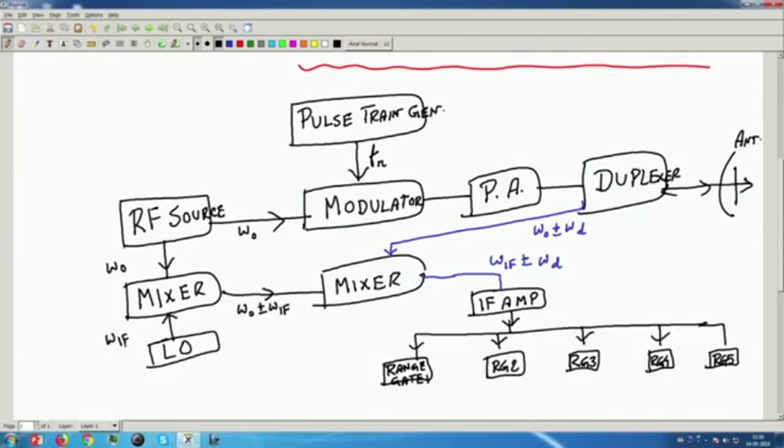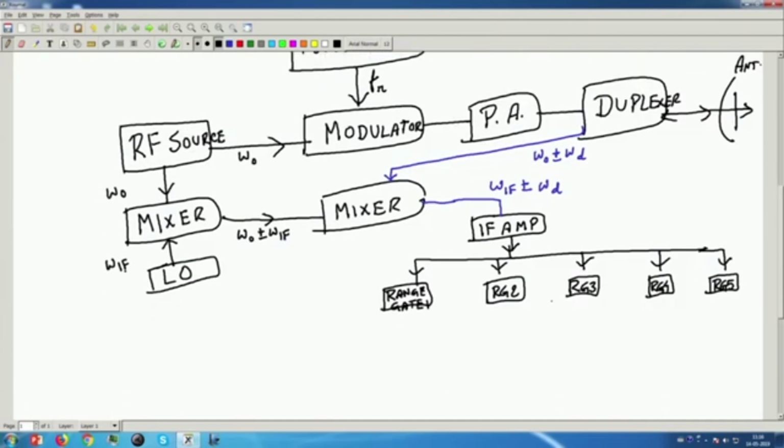The simultaneous bypass is there, but these range gates will be switched one by one. First gate 1, gate 2, depending on the range. Then we have the clutter filter we are calling, it may be an MTI filter. So, range has been extracted, now clutter filter. This may be an MTI, no problem. This same thing has been repeated at every path.